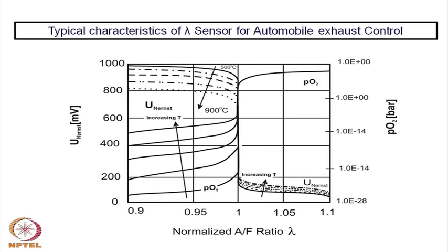However, if the carbon monoxide concentration is very high, then the catalyst life goes down, and therefore one needs to control the carbon monoxide concentration in the exhaust gas which goes into the catalytic converter. So, these two devices, the sensing device and the catalytic converter, have to work in tandem, so that combustion efficiency is achieved and the environmental problems are eliminated.